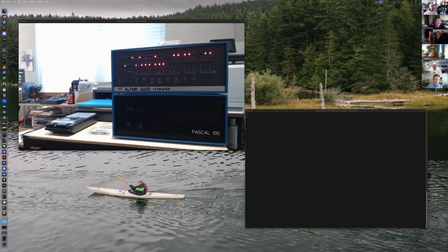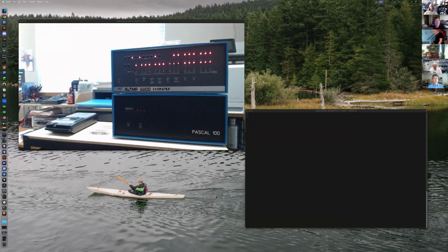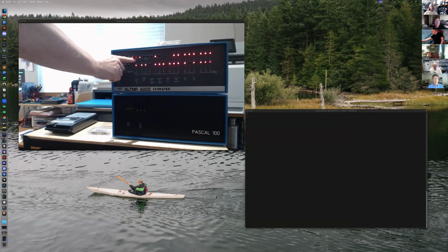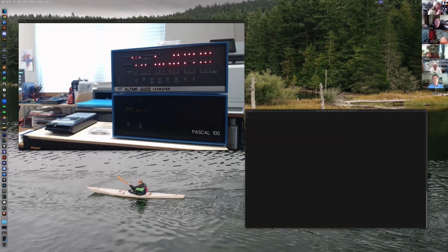Anyway, we're on the Altair. Once we get the program counter pointing at the multi-boot loader and we set the right switches on the front, then you just start the tape and start the program. When that light goes on, you can tell that it's reading. And now we wait. We've got 10 minutes before it'll finish loading.